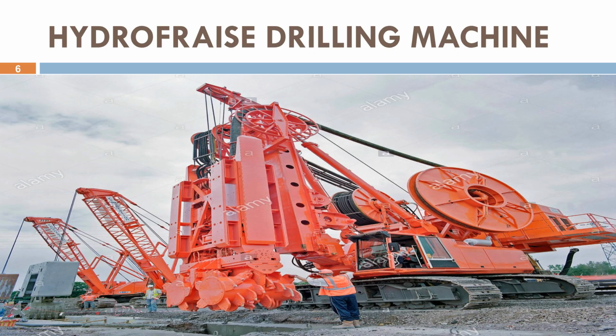This slide shows a hydrofraise drilling machine, one of the advanced machines used for diaphragm wall construction. Unlike conventional grab excavators, the hydrofraise uses rotating cutter wheels to excavate hard soil and weathered rock with high accuracy. The excavated material is transported to the surface through slurry circulation. This equipment allows engineers to construct deeper and more vertical diaphragm walls with excellent quality and dimensional accuracy.